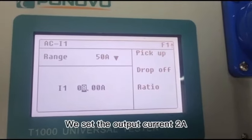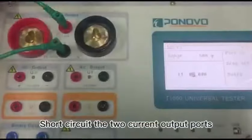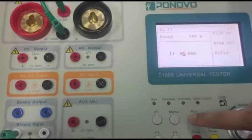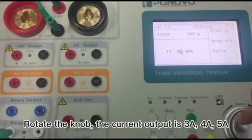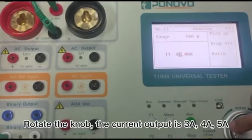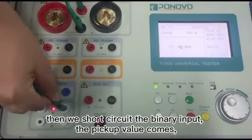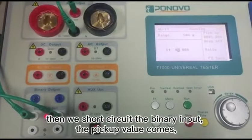We set the output current 2 amperes. Short circuit the 2 current output ports. Press run button. Rotate the knob, the current output is 3 amperes, 4 amperes, 5 amperes. Then we short circuit the binary input, the pickup value comes.